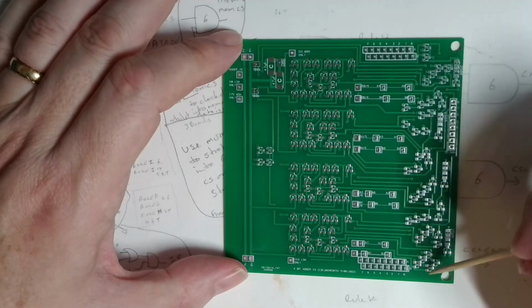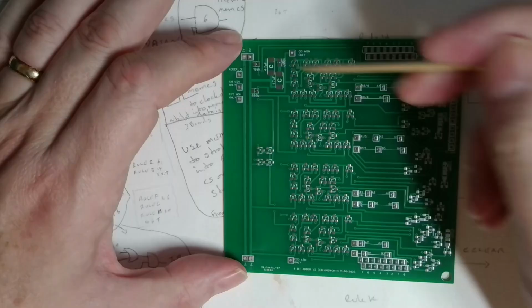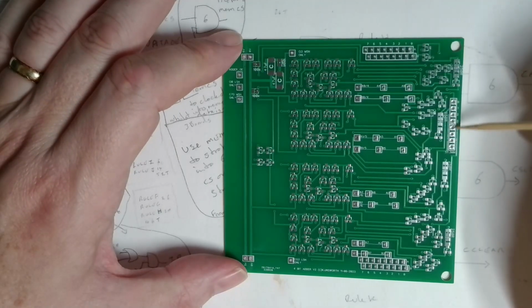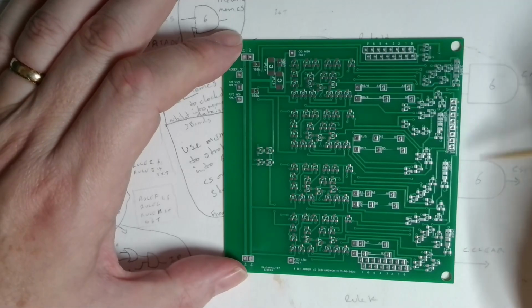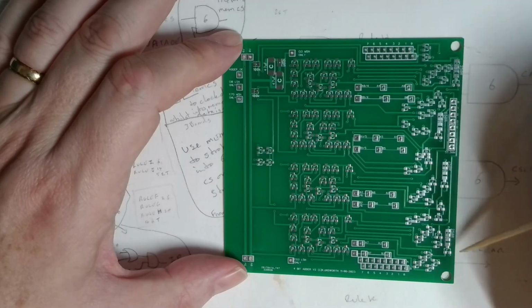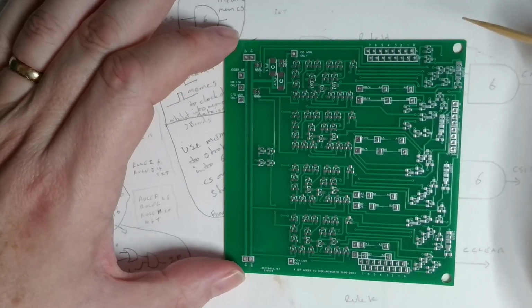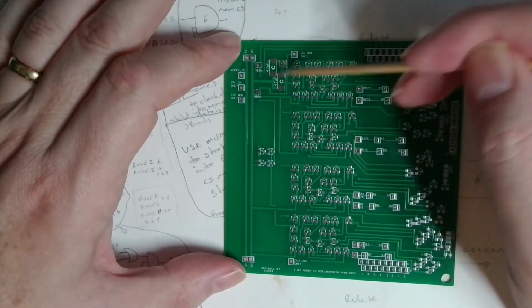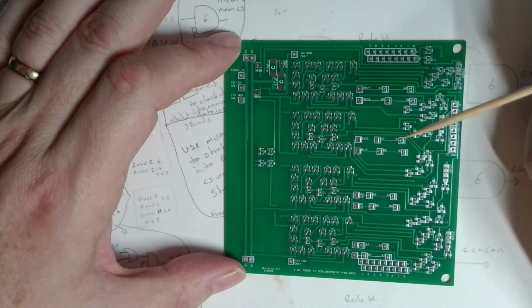All these transistors down here are tri-state outputs, which the adder output controls. And these are the nibbles going out to the data bus down here. So you either have top nibble or bottom nibble going out. There's some LEDs here as well, so you can see the bits going on and off. Over here we've got the power supply coming in and the decoupling capacitors and magic blue smoke resistor.